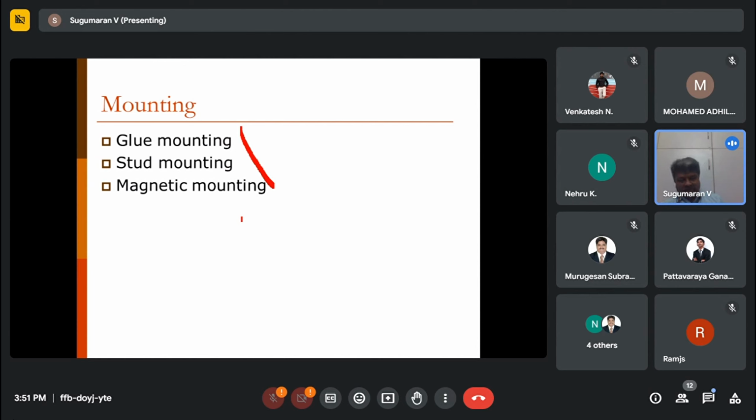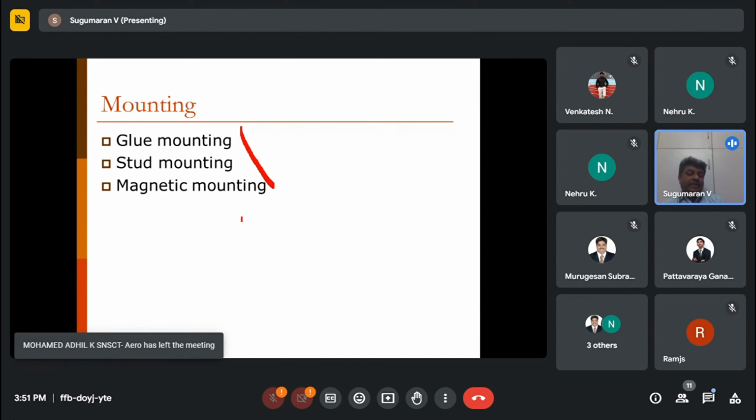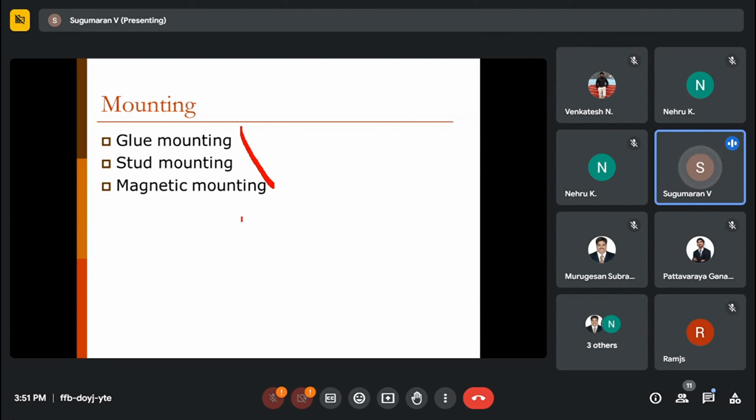Then you choose the sensor if the technical specifications are met. From the technical specification point of view, the major point that you will be matching is to find out the maximum frequency, and the dynamic range of your sensor's frequency should be capable of measuring that frequency. After meeting that technical qualification, then you check cost and nearby availability and buy. That's how you choose your sensor.